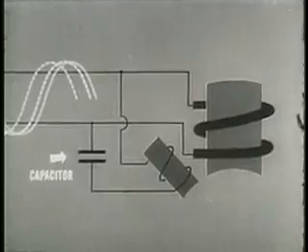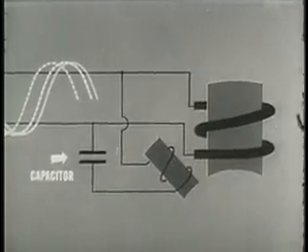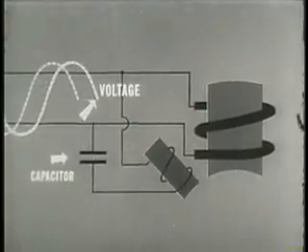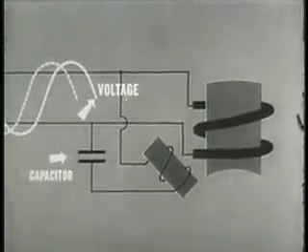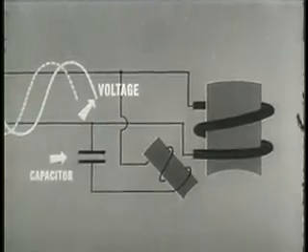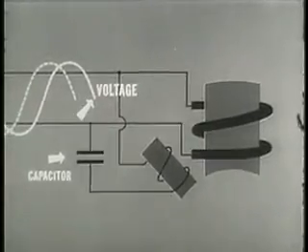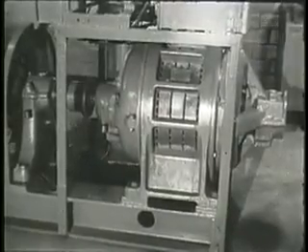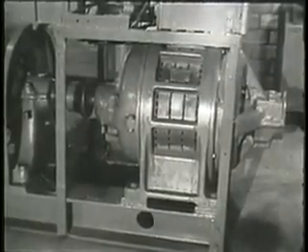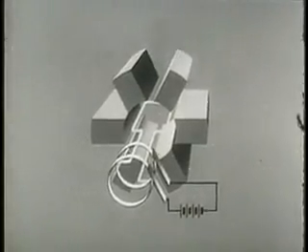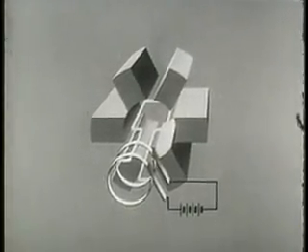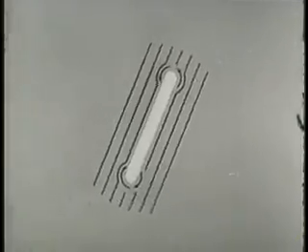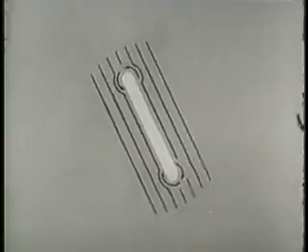In the third method, a capacitor is placed in series with a starter winding. This causes a greater phase shift between the two windings. We now have two-phase operation on single-phase voltage. In synchronous motors, there is no need for relative motion. The EMF needed for the rotor is supplied from an outside DC source. Here, the rotor and the revolving field rotate at the same speed.